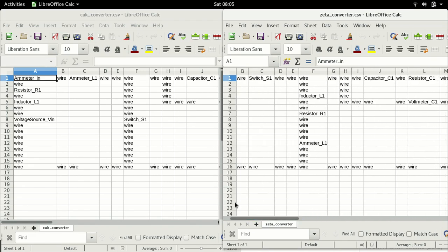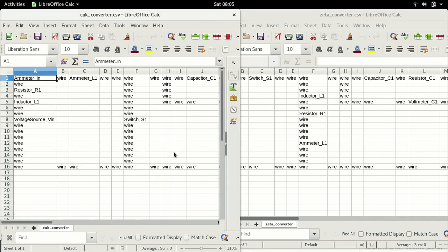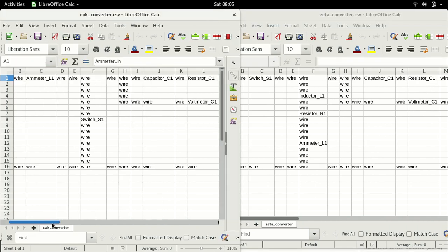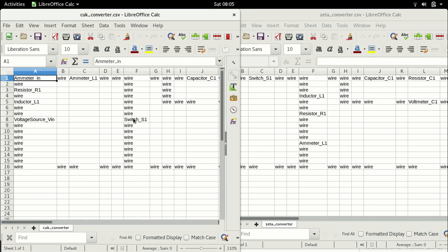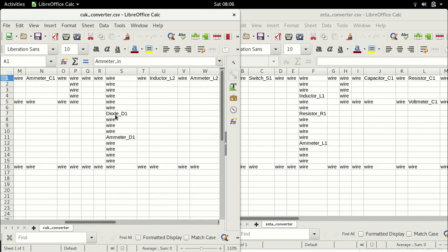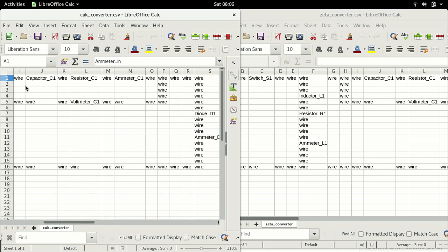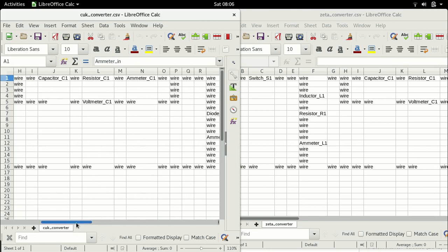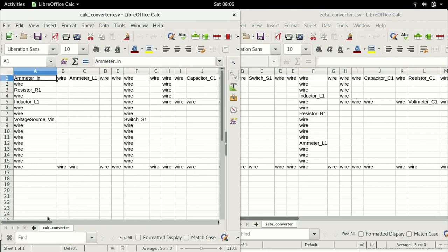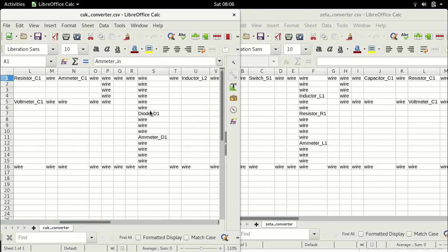Now, when the switch is turned off here, the voltage source will now charge this capacitor through the diode, because the polarity of the diode is downwards. So therefore the diode will form a low resistance path for the current that is charging this capacitor. So the input voltage charges the capacitor through the diode, through the freewheeling diode.